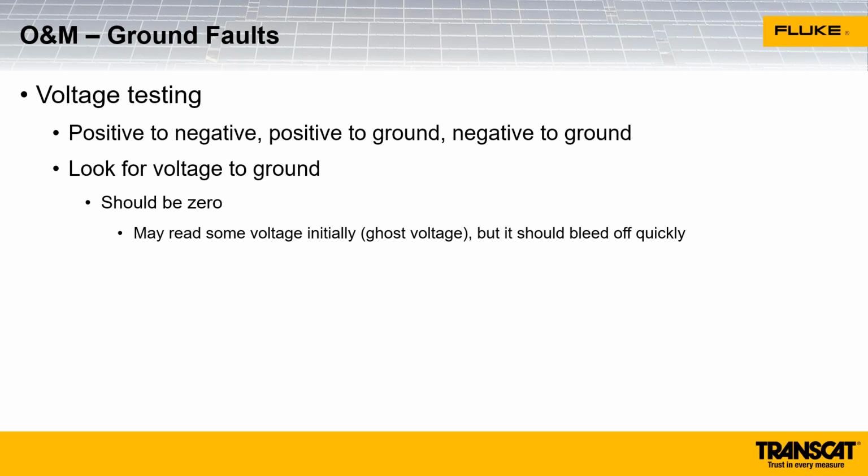You may initially see some voltage. This is called ghost voltage, but that will bleed off pretty quickly. And what we're really looking for is true voltage, not the ghost voltage.